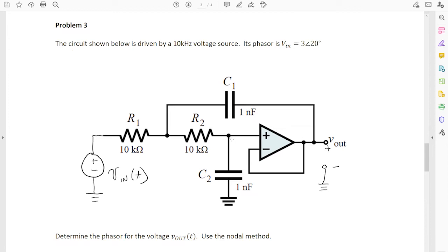So in this case, what you know is that this plus terminal is at V out. Okay. Wait, you say the node equals V out? So yeah, the critical thing here is V minus. What do we always know? V minus and V plus are the same. Somehow, some way, there's got to be a way for me to fix V plus or V minus.